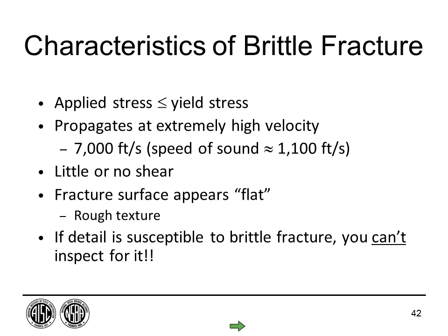Some things to keep in mind about brittle fracture, which is much different than fatigue, right? We test for fatigue and run tests for months at a time, getting cracks to grow. Brittle fracture is not like that. Applied stresses also can be low. They don't have to be high. But note this. Look how fast the crack actually runs through the material, right? Much faster than the speed of sound. Little or no shear. That just simply means there's no ductility. There's no shear lips on the specimen. In fact, when you look at the fracture surfaces, they actually appear flat, as if someone cut them with a saw at times.